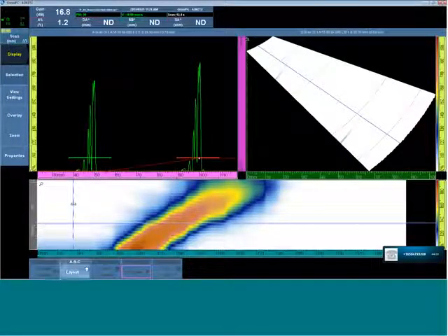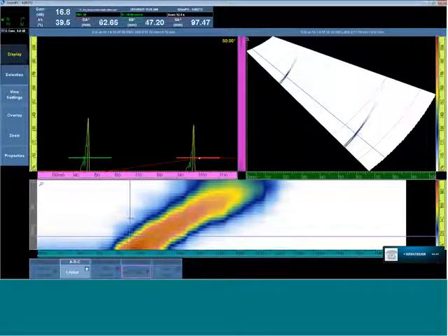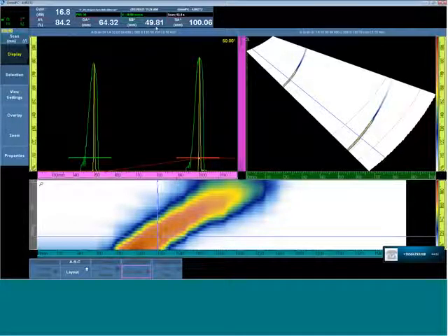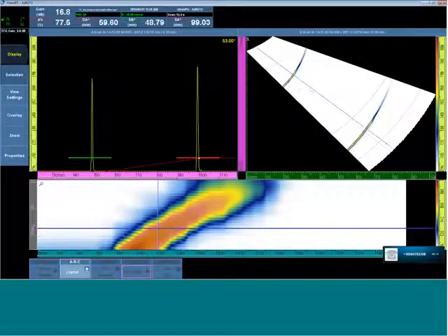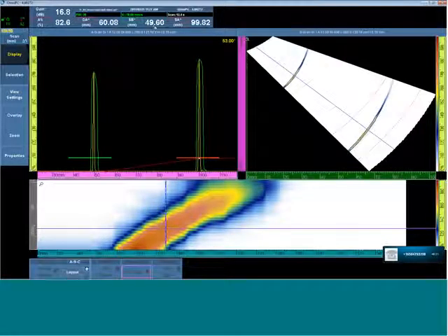On any A-scan, we'll start at 50 degrees. We need to achieve 50 millimeters and 100 millimeters on the cal block. That's only possible if the wedge delay and velocity are accurately entered into the software, either through the wizard or through the calculator initially in the group setup wizards. Moving to a different angle, 50, 100. So we can prove that for 45 to 70 degrees.